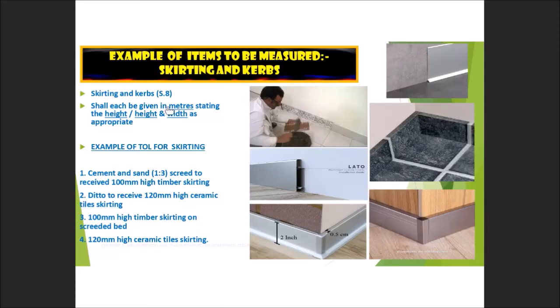Okay, skirting and the curve is stated under S.8. You can refer to S.8 given in meter, but remember to state the height. This one also had been emphasized when you measure for the skirting inside the staircase in the previous lecture. You can write down the description, but don't forget to add in the height of the skirting. The rule of measurement is similar.